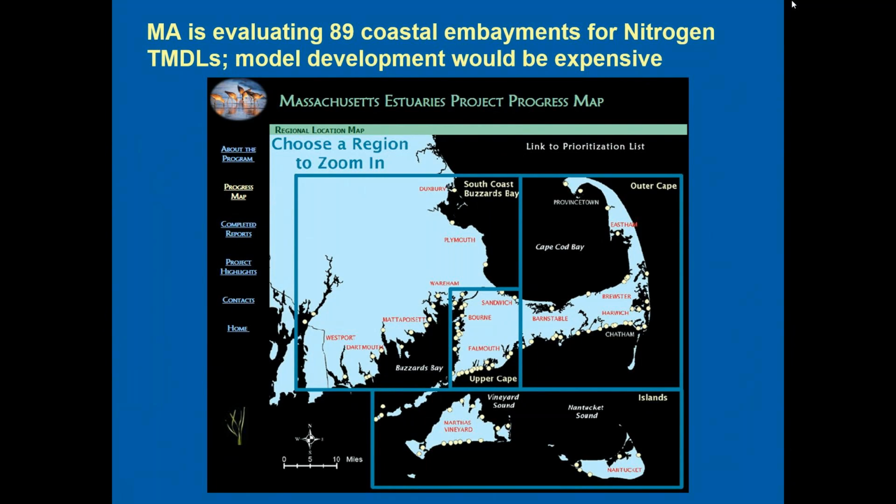Developing detailed rainfall runoff models for each watershed would have been cost prohibitive. So MassDOT used SELDM to develop an average annual loading rate per acre of pavement and to calculate loads by using the area of state-owned roads in each contributing area.